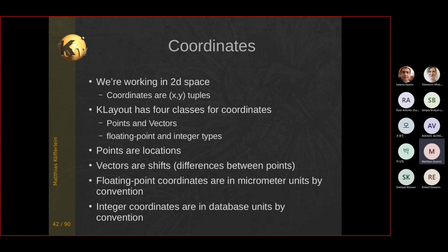And in order to have some freedom, one uses 1 nanometer, for example, because we believe that we don't need coordinates which are fractions of nanometers. Today's technologies are, let's say, if we go down to 5 or 7 nanometer, then it seems like choosing 1 nanometer as the basic unit is a bit coarse. So that's why people tend to go to half a nanometer or quarter of a nanometer today. But basically, we are talking about a very small number.